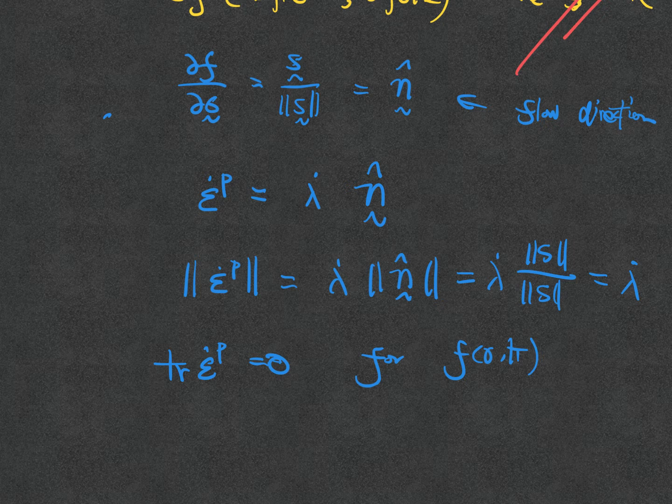U surface. That only depends on the measure of the stress. Okay, now this is not good for modeling soil, or even for metal at very high pressure, because if you subject something to a lot of compaction pressure, it always shows some pressure dependence. But J2 plasticity is the first model to derive, and it actually works a lot for metal. It doesn't work for soil. Hence it's worth talking about, and it's easier to understand. Okay, so far so good.